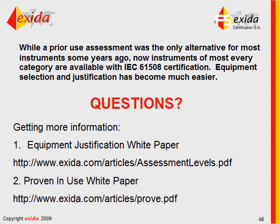Don't do it unless it's been certified. That's just a real bad idea. That's why you got to use proven in use or certification for safety integrity. In fact, when you think about the application requirements, you really ought to do some kind of non-critical testing of all instruments before you use them in safety critical applications.